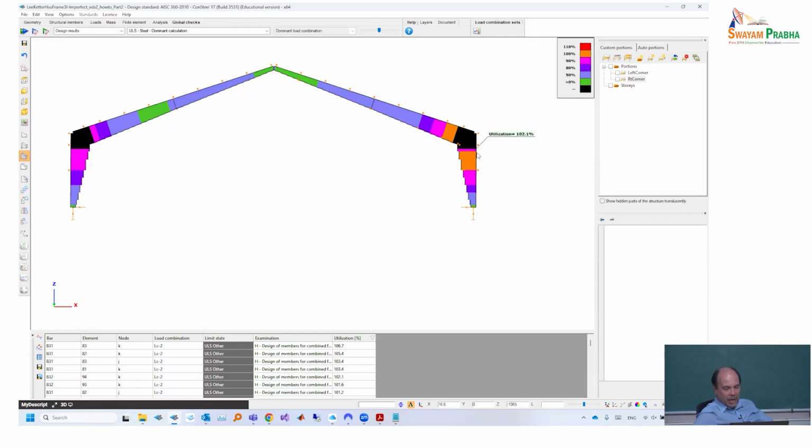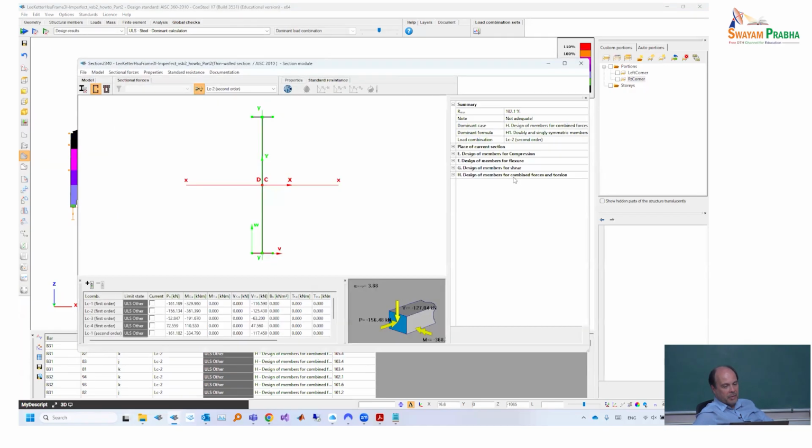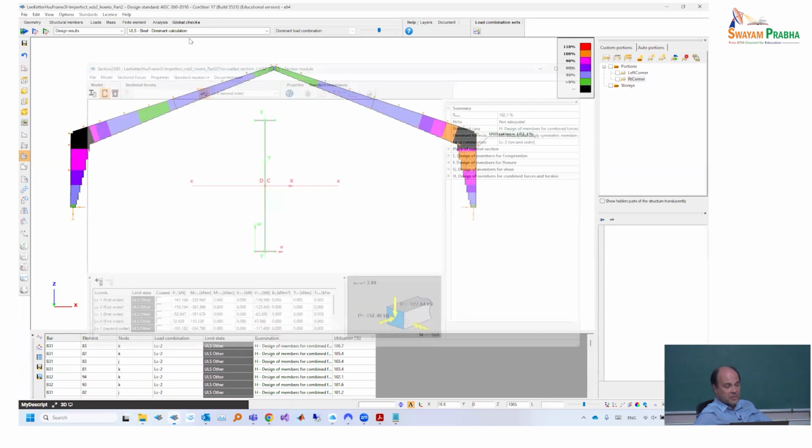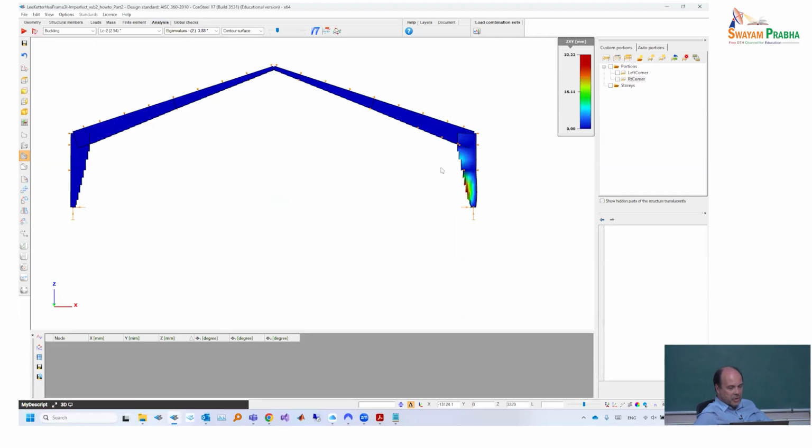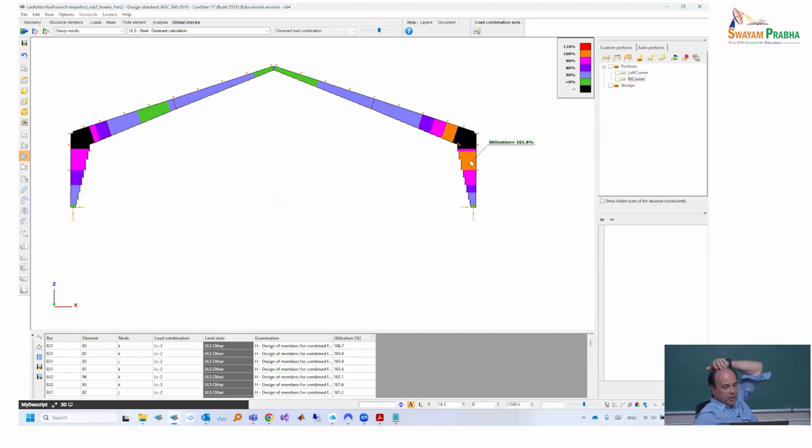But if we go again to this cross-section, what we wanted, then we will see that now, nicely, without saying anything, not the very first mode was used for the column, but something else. Let's see what was the 3.88. 3.88 is definitely the second buckling mode, which belongs to the column. Okay? So the first is still to the rafter, without me selecting this mode and forcing the calculation to be performed for this mode, Consteel was automatically using this mode for the column.